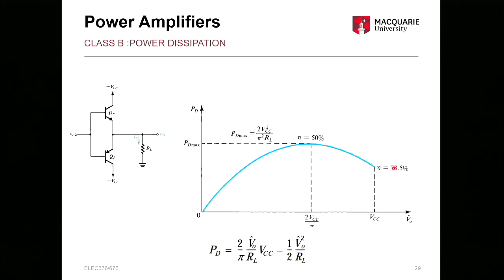And you can see right at the top of this curve, we have our peak in efficiency of VCC. This is the region we want to be operating in, where we have high efficiency, but also high output. If we're over here, then we have low output. That's not what the power amp's designed to do.